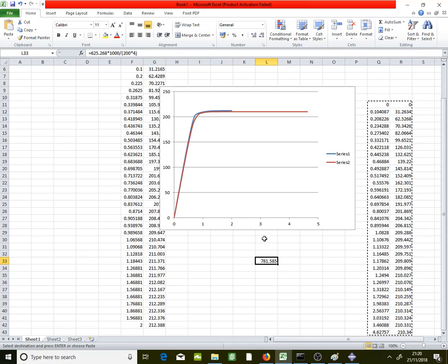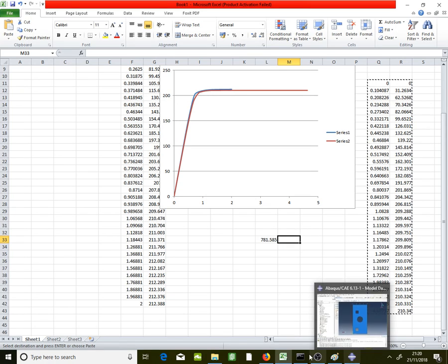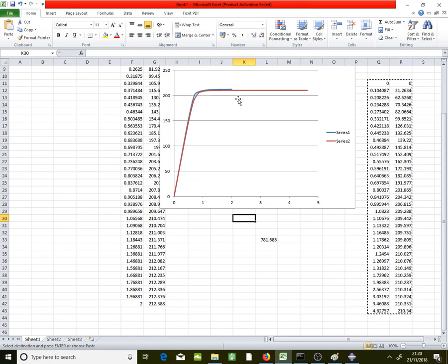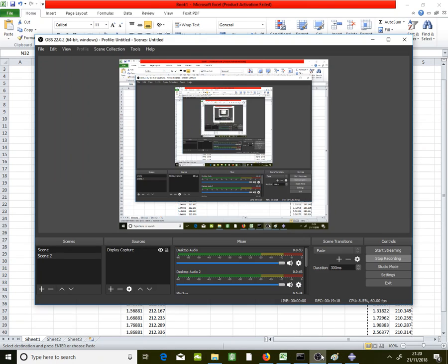So previously the load of 625 is not the full load that can be applied in the element, so the maximum load was 210, as you can see here. By comparison, they get almost the same behavior whether you have displacement control or load control. Sometimes the load cannot be continued, so an aborted analysis does not mean it is not working, it means it has reached an ultimate load. Thank you very much.